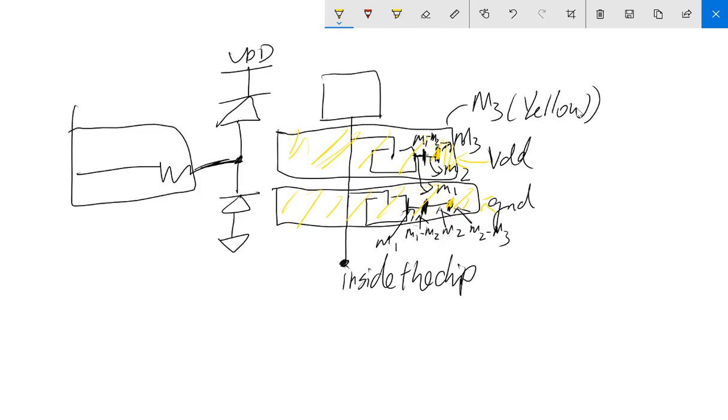And because this is VDD, you can imagine this VDD the same as this VDD. So this node here should be what? Should be the Pwell. So you need an N act, and no, you need an N. So that's a P act and N well. So this should be a P act and N well, right? And this should be an N act. Okay, so now you know which one should be placed where. And now let's see if this is right.